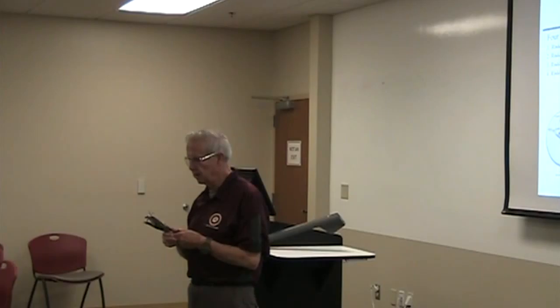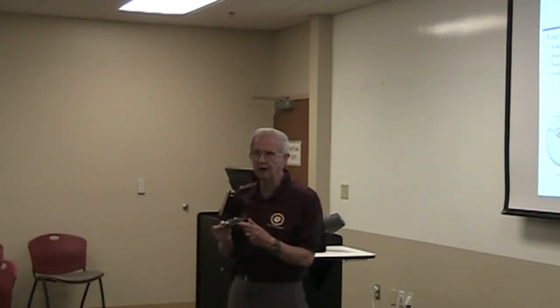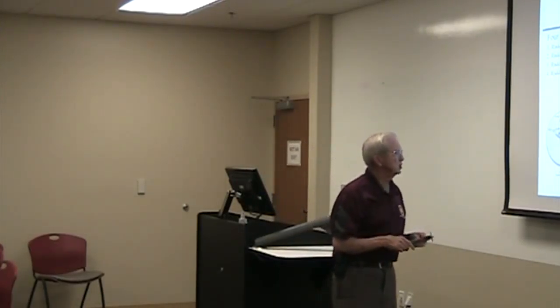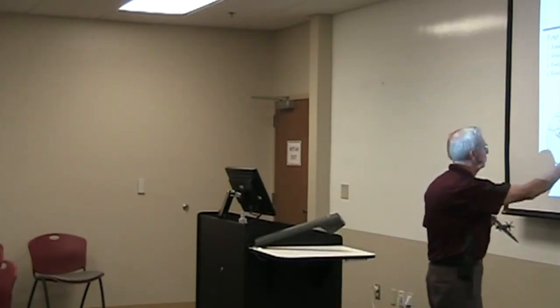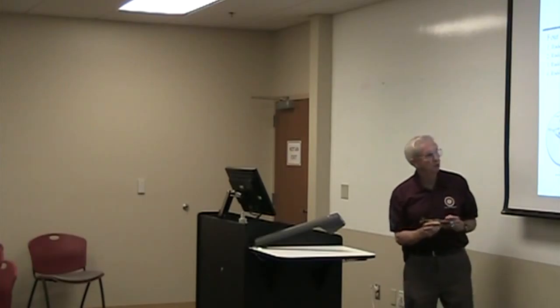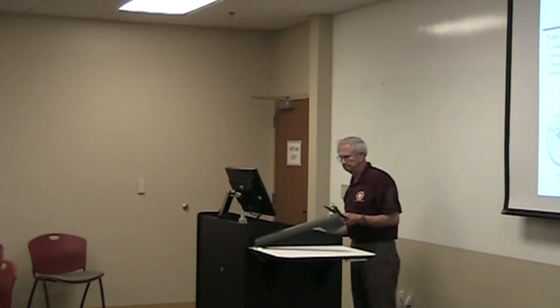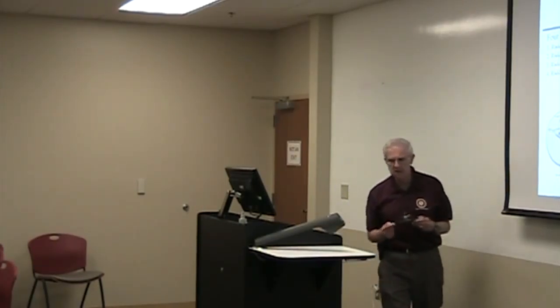You have to hold right rudder. So you have to be able to counteract that, and we call that P factor, and it's due to slipstream rotation and that sort of thing. And the fact that the downgoing blade of the propeller produces more thrust than the upgoing blade.